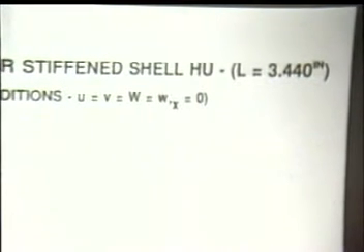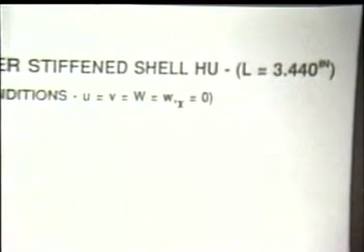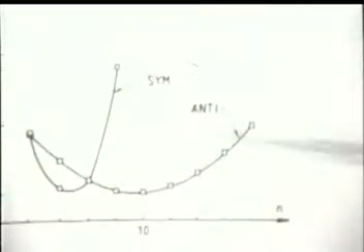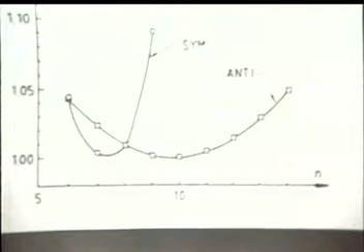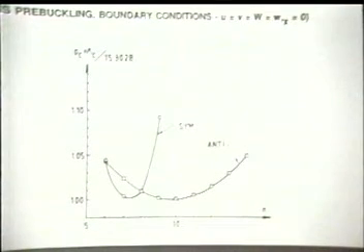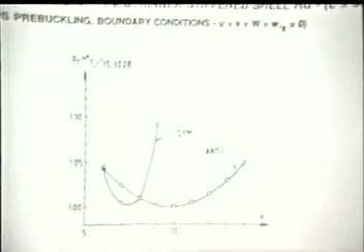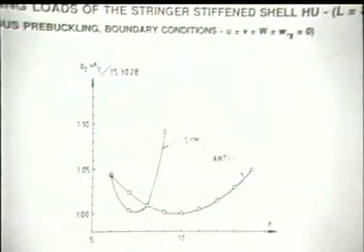Okay, now, if you do a study of different buckling modes, if you solve for simultaneous buckling modes, I have to say here, I didn't say anything about the numerical method used. Maybe I shall say a word. The response problems, which are a pre-buckling problem and the post-buckling problem, are solved by the standard shooting method, parallel shooting, with a certain number of intervals as needed.